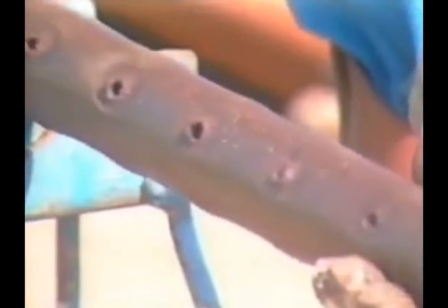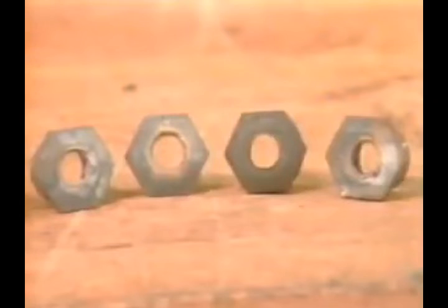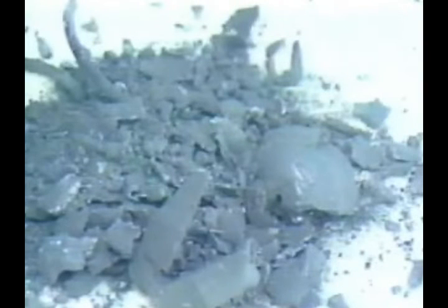An inspection of the port plug holes, or scallops, will indicate if the charges have fired properly. A round hole near the center of the port plug, or scallop, indicates that the charge was correctly aligned and properly functioning. Any charge debris left in the carrier should be relatively small fragments. Practically whole charge cases indicate low order firing of the charge.